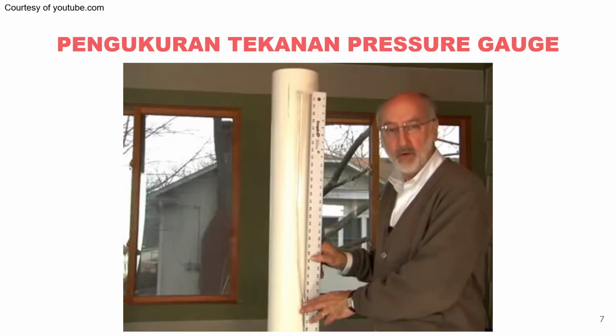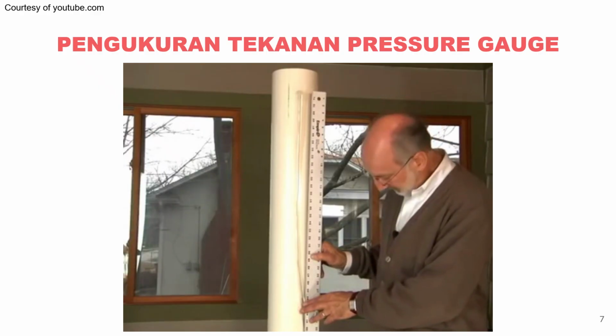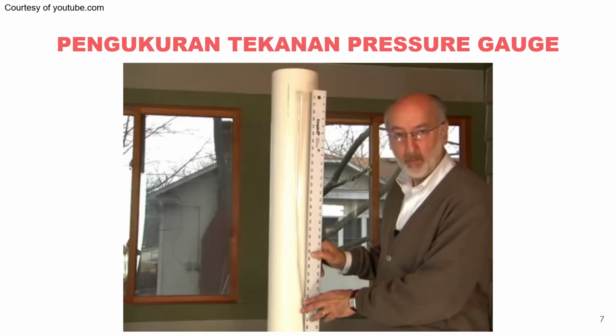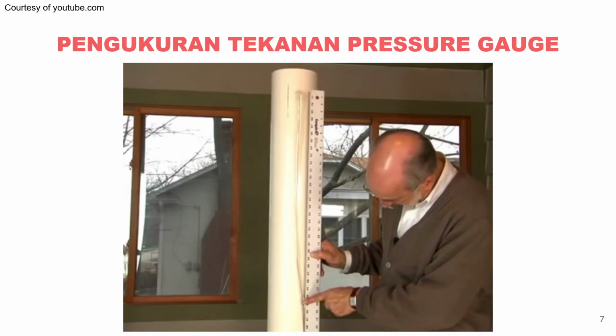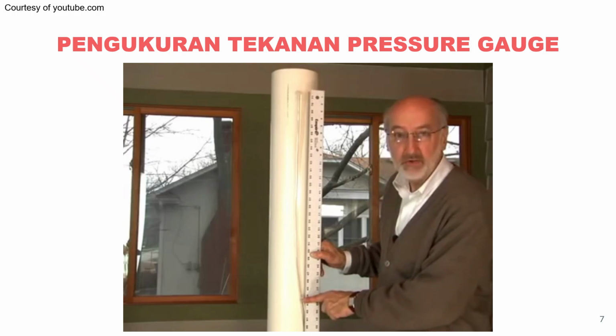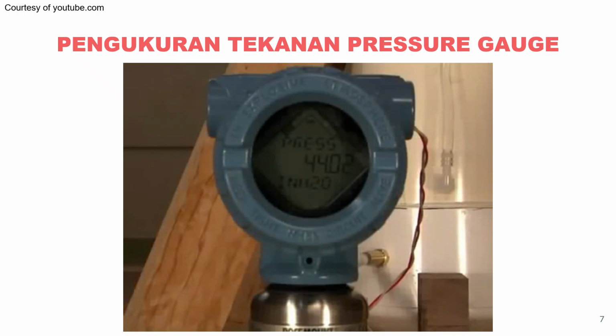Now that we've got the water in the tank, let's see how close we really are to the actual measurement. If I lift the ruler a little bit off the bottom to compensate for the thickness of the bottom of the cap, I would say that the reading, according to the sight glass, is just about 44 inches.